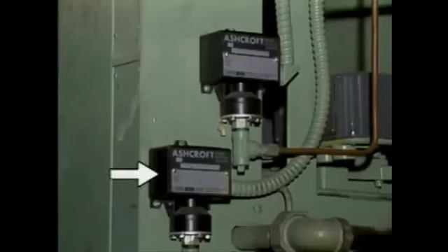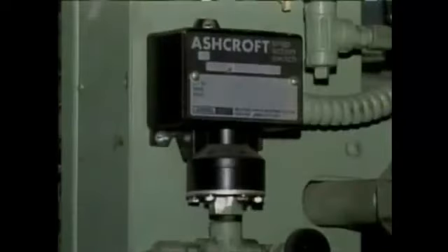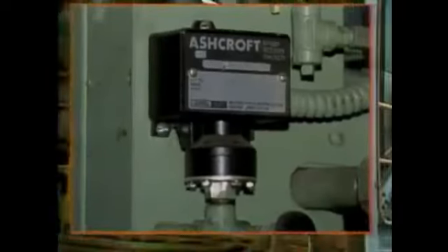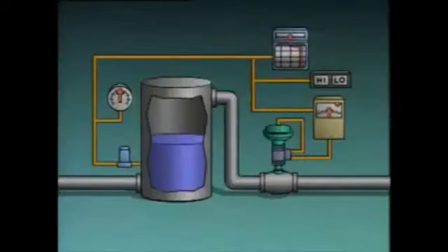A switch may also be used as an interlock. An interlock ensures that a predetermined set of conditions exists before the status of equipment is changed to prevent equipment damage or harm to personnel. For example, this fan could be damaged if it's operated without proper lubrication. To prevent damage, an interlock pressure switch opens to shut off the fan's motor when the oil pressure in the motor is too low. The switch remains open to keep operators from turning on the fan by mistake until the oil pressure is high enough for normal operation.